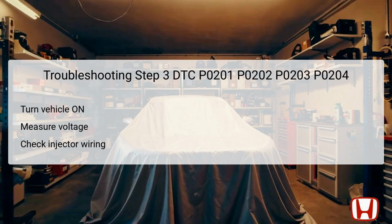For step 3, the process continues with checking for any open wires in the injector circuit. Begin by again turning the vehicle to the on mode. You must ensure the injector 2P connector for the problematic cylinder remains disconnected during this portion of the troubleshooting. Measure the voltage between test points 1 and 2.